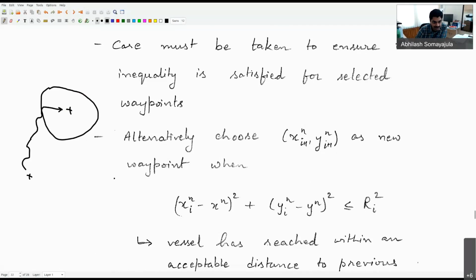Okay. Or the other approach is, I have given it some 3 waypoints. It's going from here to here. When it reaches inside a certain region of radius, I ask it to now start moving towards this next one. Okay, both of those methods are quite popular. In fact, the second one is more popular, where it has reached one waypoint, and then you specify that it go to the next waypoint. You have a certain circle around the destination waypoint. If it reaches within that circle, you say, okay, now you can please go ahead to the next waypoint.